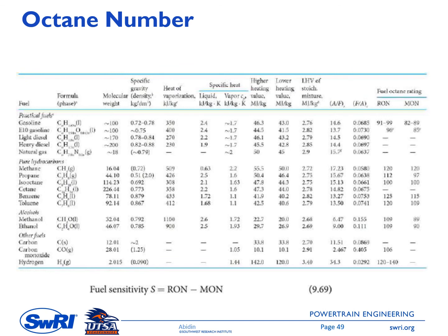Now you know the meaning of octane number. So when you purchase your car fuel, you can check the fuel octane number required by your car. In the US, the octane number is usually the average of RON and MON, so this is RON plus MON over 2. In Europe and in Asian countries, usually they use RON to represent the fuel octane number at the fuel station.